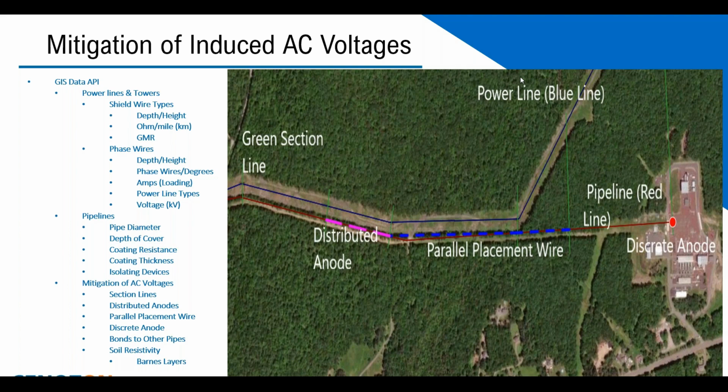Then we've got our surface, where we could have conductive faults and things of this nature, and then we have the deep layer where the inductive voltages are usually measured, and that could vary, but typically it's about 30 meters in depth, to get a better assessment.